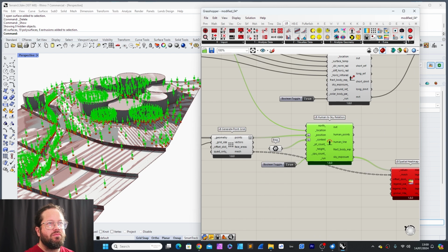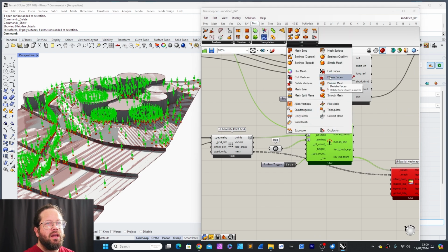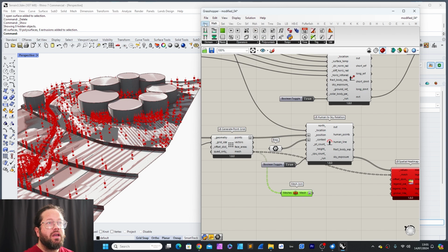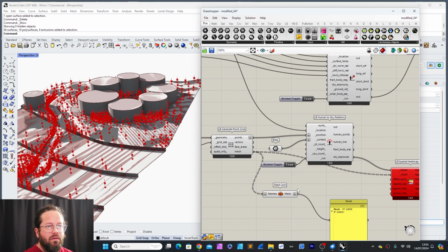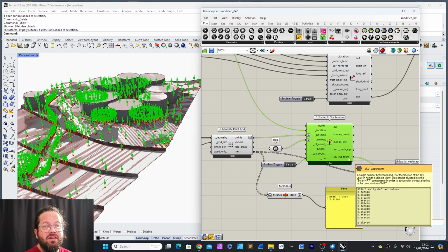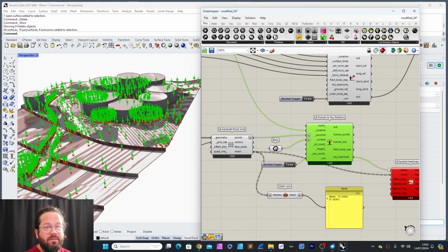So what we're going to do is we take the mesh and join the mesh. We join the mesh and flatten it. I hope I can, let's see. No. Okay, flatten. Now we're talking. So I had to flatten the meshes first and then combine the meshes. So we get one mesh with 3,260 faces, and that correlates with the 3,260 values going in here.